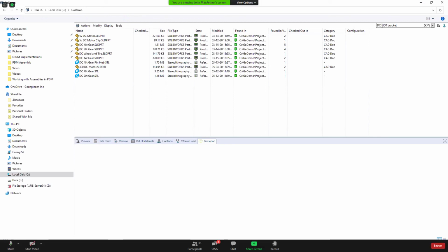So question on an upgrade from 2019 to 2020, is it mandatory that users check in their files before the upgrade? I would not say the word mandatory, no. It's recommended, and I do believe it is a good idea to have people check in their work, but realistically, if there's a file checked out on a hard drive to a local view, the server gets upgraded. In fact, you can even do a server move, and when the server's been reattached to the local view, it will just check in and continue to work.